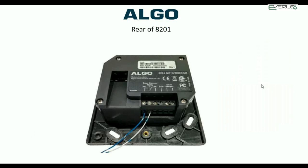If we have a look at the rear of the unit, just wanted to point out a couple of things here for you. This here is where the PoE network cable goes in. So that's your network connection. Over here is your door control. It's your relay that controls the external lock mechanisms. So it's just dry contact. You've got a normally open, normally closed. And it's got a door sensor there, so you could use that for indicating if the door is opened or closed.